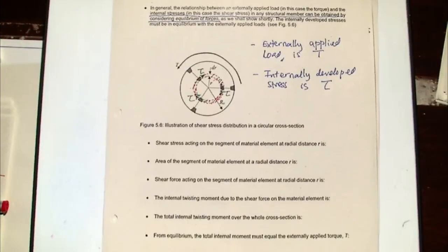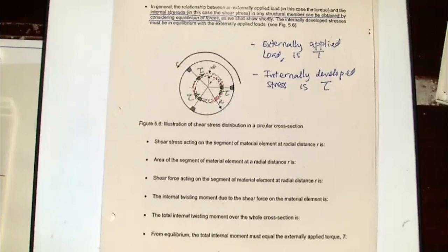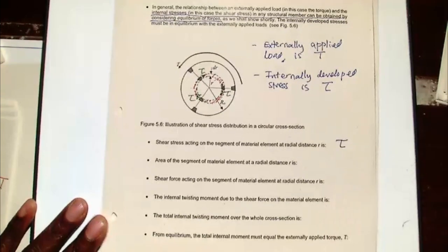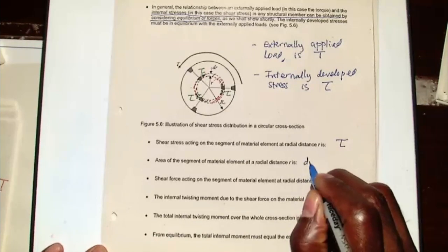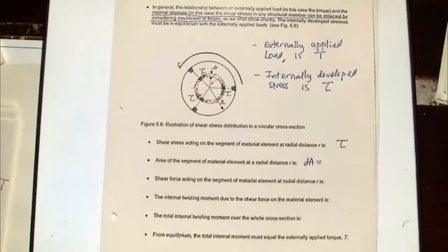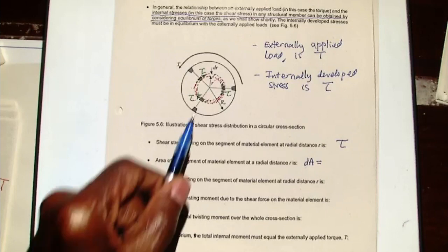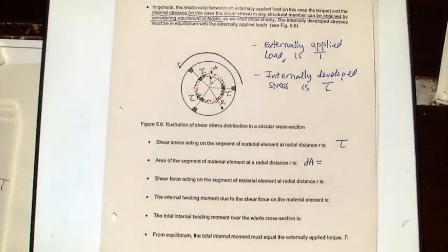So if you look at that small layer, the shear stress acting on it is denoted by tau. The area of that small ring would be what? If you look at that ring, it's inner radius of small r, thickness of dr. So if you are trying to find the surface area of that ring of material, what should that be? Pi over? Pi 2r. Correct. So do we all see that?